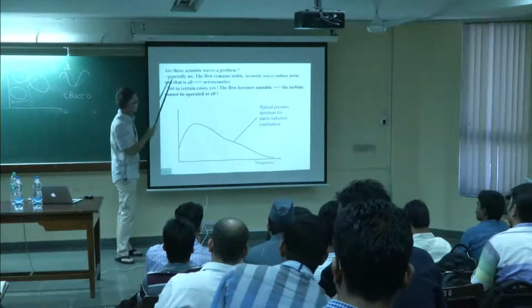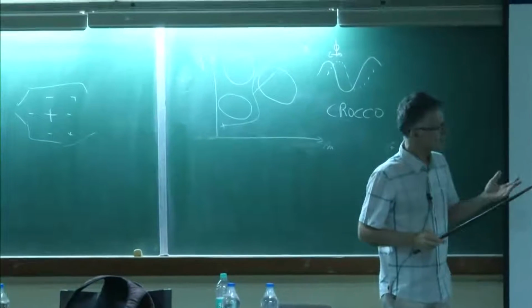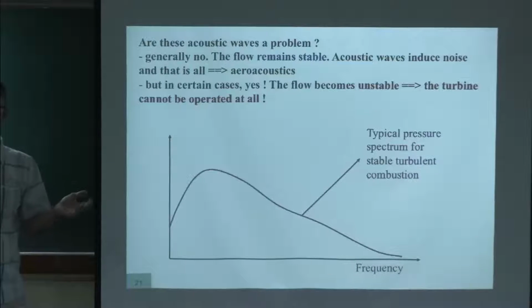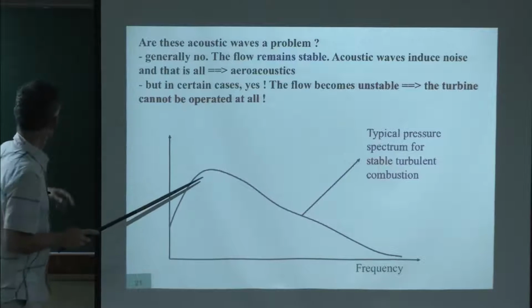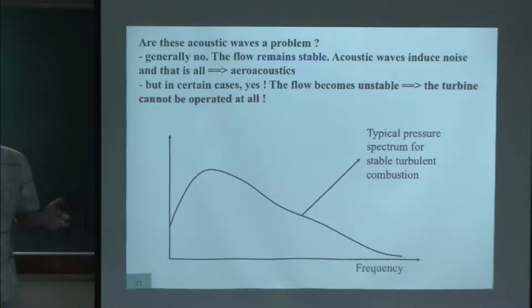So, are these acoustic waves a problem? In general, you have acoustic waves in a burner. They are not a problem if the Rayleigh criterion is not satisfied. You have a spectrum, which is the one I've shown you before. It makes noise, broadband noise, and that's all.